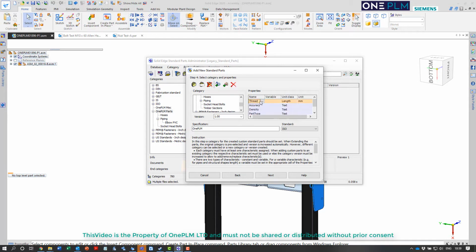So it's quite obvious on here which ones we're going to do, so let's delete the ones that have been brought down from the 1PLM parts, and then we're going to find obviously height and width to match the options from the other ones. So remember, we can use this as a drop down, and we need to make sure these are both length on here. So normally you can just start typing and it will find the appropriate one. So we've got height, width,